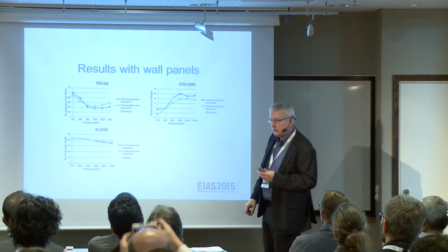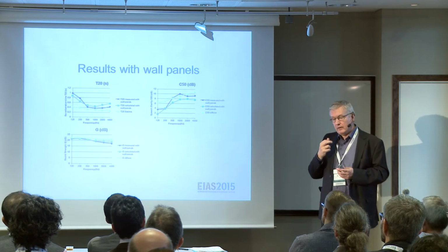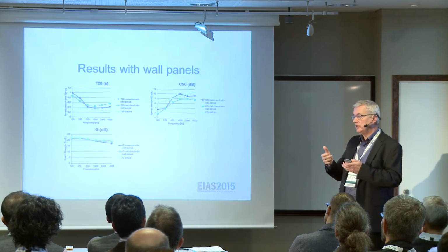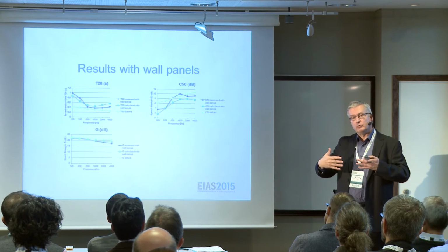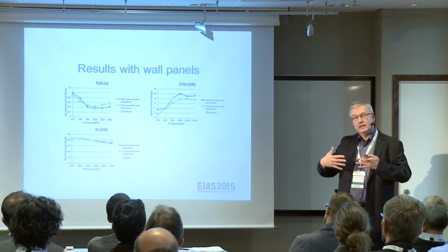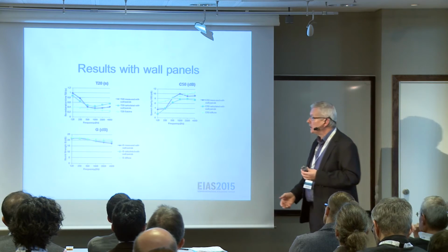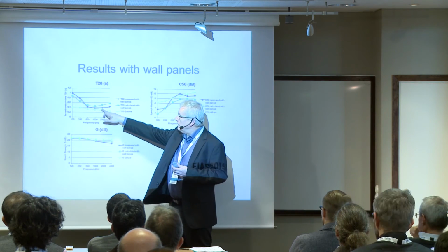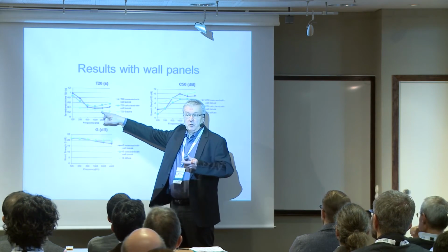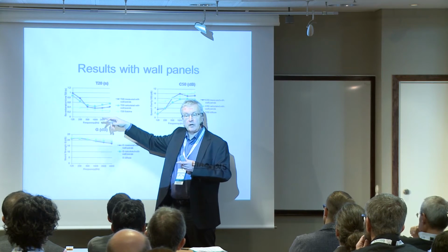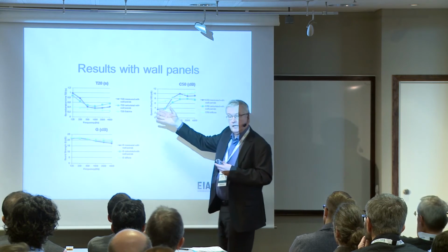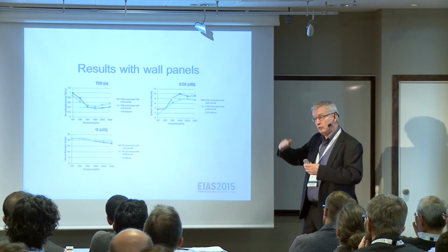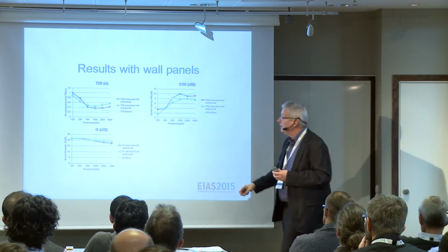But what is interesting to see is that when we have this subdivision into the grazing and non-grazing field, then the effect of the wall panel is more pronounced in these calculations than if you do a Sabine calculation, because adding the wall panels in the Sabine calculation, you don't see it. It's too little area. But the real effect, as you saw in the demonstration, is quite huge, and that is what you see in this model.